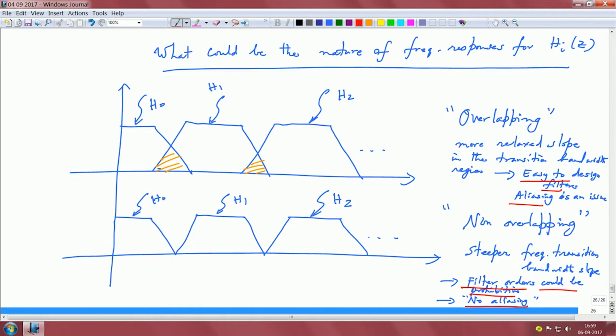When we design digital filter banks, we can overcome these aliasing errors and have overlapping frequency responses, but we design our synthesis filters somehow to cancel aliasing using our multi-rate operations. So, I think that is the whole idea in the design of these filter banks.